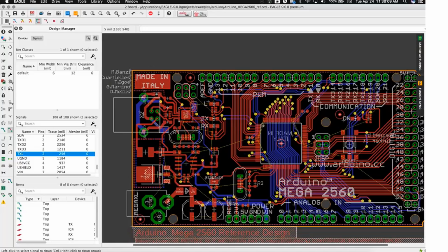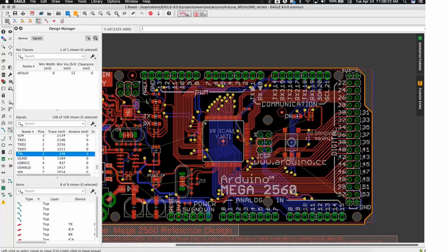Likewise, we added things like ripping up connections between components, because oftentimes I might decide, hey, I've got this processor, that's fine, but I'm going to rip up the connections between that processor and, let's say, this connector over here. It's relatively straightforward then for me to say, I want to change that connector.